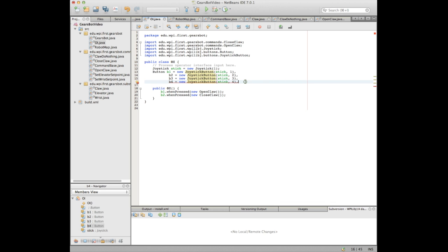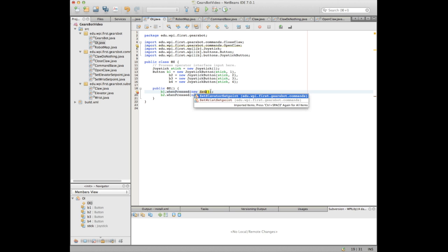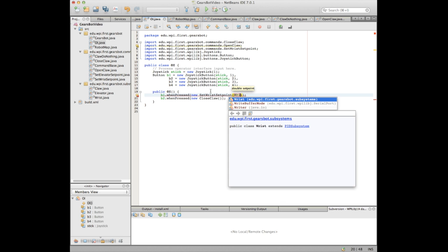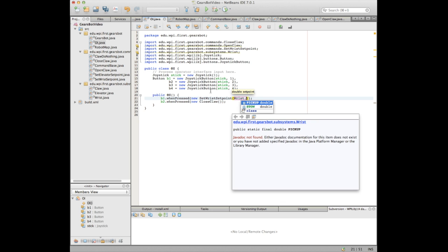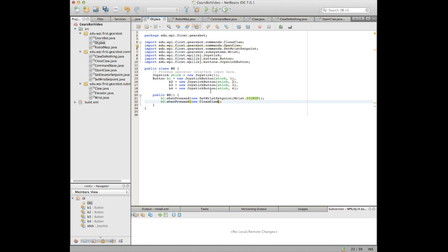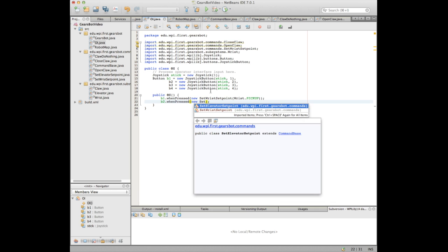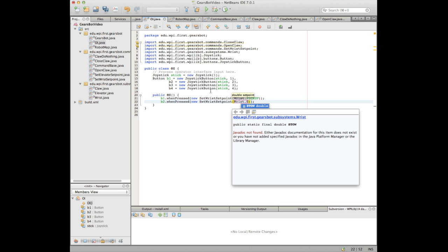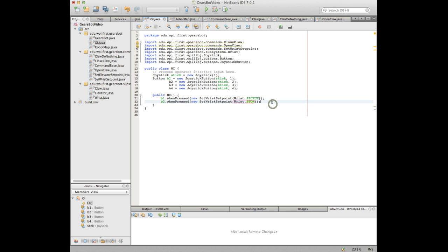And now one of the nice things about how buttons work is we can just rebind the command. So we can set. You want to make these be 3 and 4? We can do all 4. Oh, okay. Because you want to be able to go back and forth. Okay. So the first one, when you press button 1, we'll set the wrist to pick up, and then button 2 will tell the wrist to stow. So these are those parameters that we put into the commands before that say where it should go, that it's using to do the tolerance and using to set the set point. So you can see how they're used here.